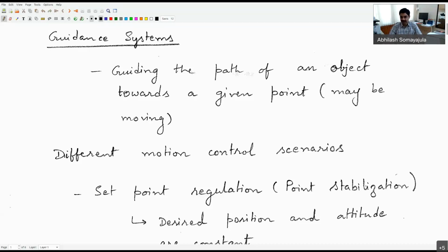We will not be looking at a hydrodynamic derivative approach because we have not done experiments as yet on our craft in order to determine them, so we don't know them precisely. We can only get those values from other experiments which others have done. But for now, we will create our modeling based on a first principles approach using the nonlinear damping in surge and the cross flow drag principles.